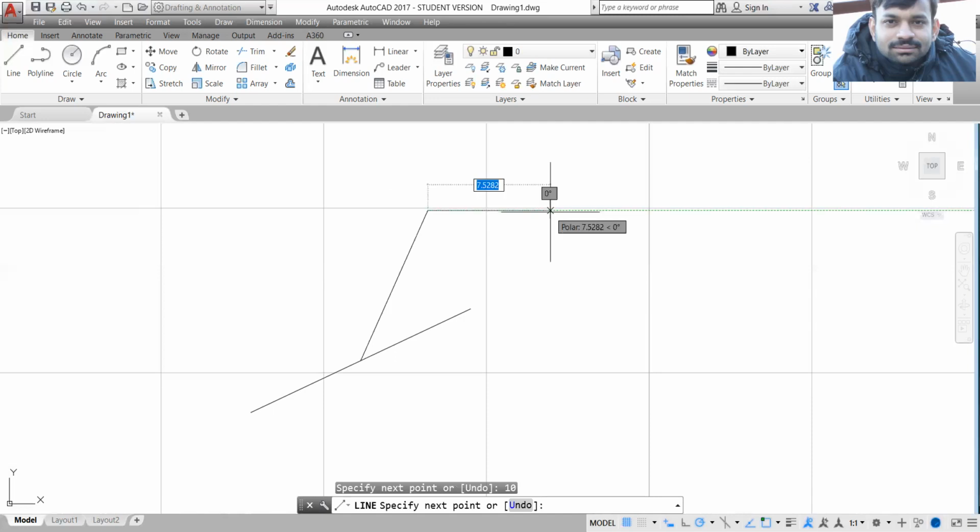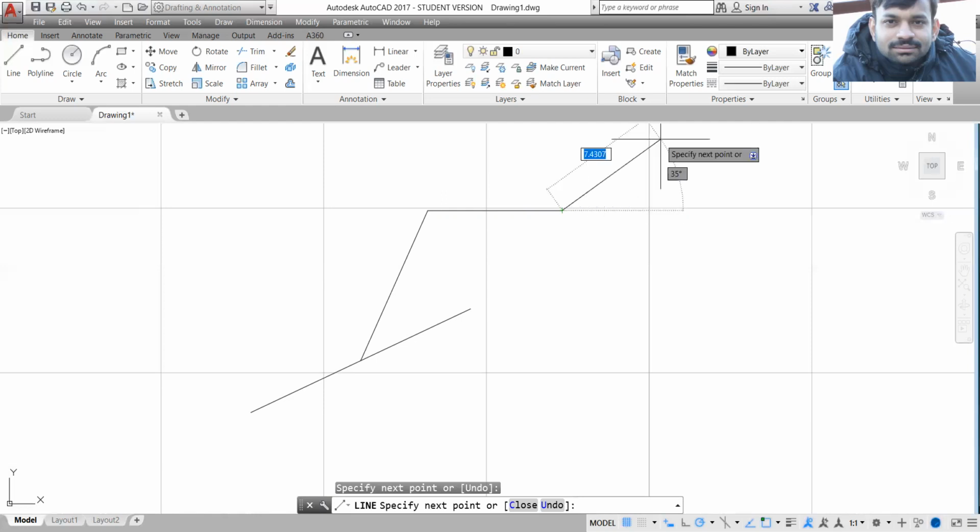Now we have seen the use of two boxes along with the crosshair. The first box suggests the next step that is to be done. The second box gives the length of the line. Let's talk about the third box now. For example, I want to draw a line whose length is 5 centimeters and which is aligned at an angle of 45° from the positive x-axis.